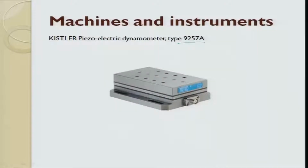Now this is a Kistler make piezoelectric dynamometer type 9257A. It measures forces in 3 directions: X, Y and Z. In this case, because this dynamometer is mounted horizontally, we have forces in these directions.